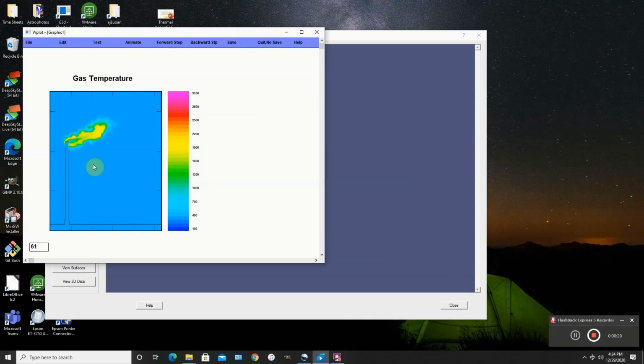Now, I don't know whether I mentioned it or not, but the combustion model is set up so that ignition occurs at room temperature. You don't need to apply a high temperature pilot to get the ignition going. And the reason for doing that is for user convenience. If you want to run an ignition problem, you need to modify the combustion model somewhat to do ignition. But for convenience, we're running it so that it burns at room temperature. So you can see that the flare is coming out and it's flowing out of the zone. And this is a slice right down the center plane.